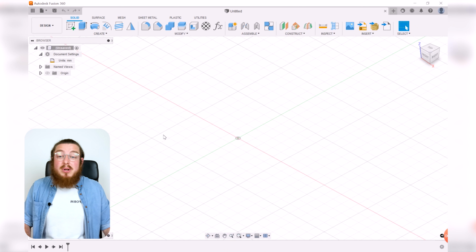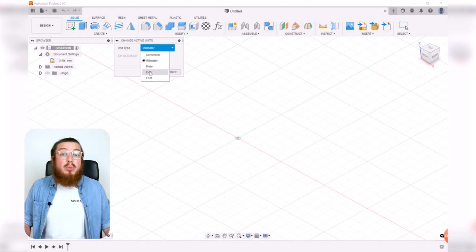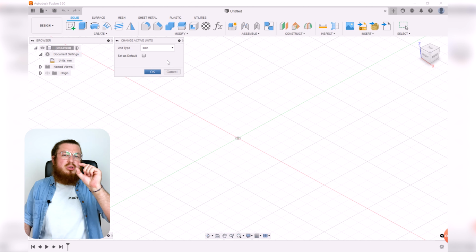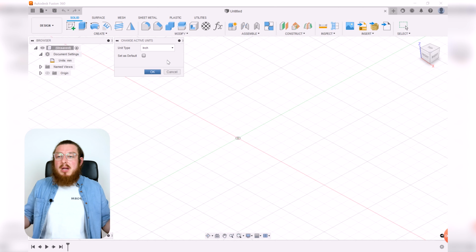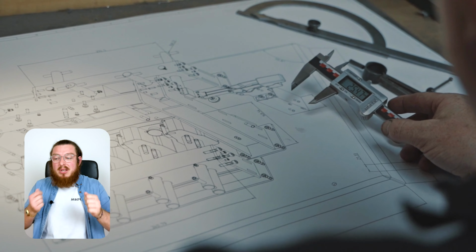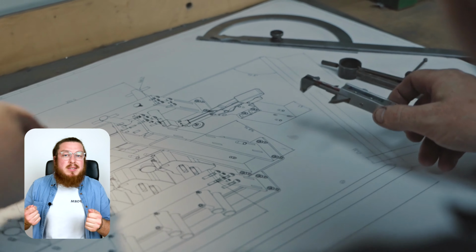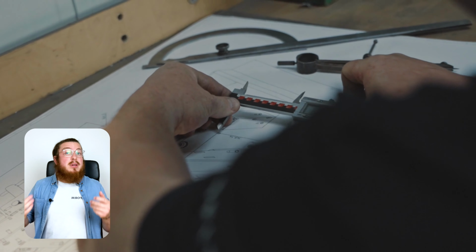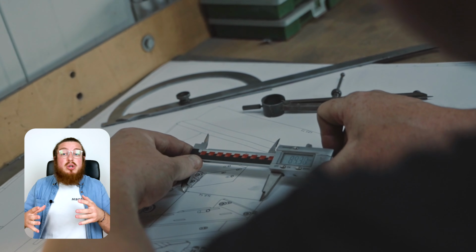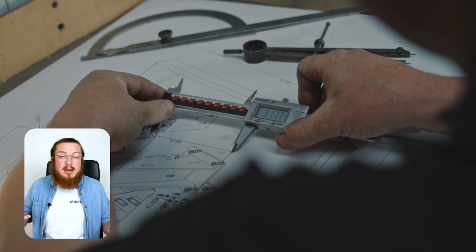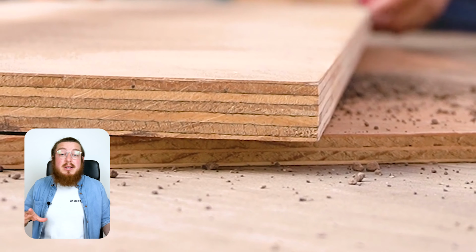So the first thing we'll want to do is change over our units from millimeters to inches. Like I said, that bounding box that we'll be using, or the molding box, is usually made from foam core that's about 1/4 inch or so, and because you always want to be working with CAD with some kind of physical tangibility, working with material that already exists in real life is a really good way to scale exactly how large or how small things feel.